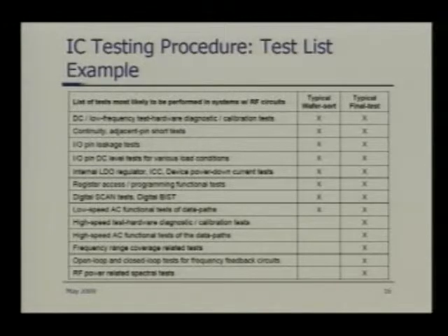All of them have the same importance. These ICC measurements all have the same importance with respect to the RF test as the IO pin leakage test. If the internal circuit node is leaking because of some process variation or some bridging fault, bridging between two circuit nodes, resistive bridging, there will be an increase in the leakage, and most likely it's not going to run at a higher frequency. So the device power down current test is also a good indicator of RF frequency performance.